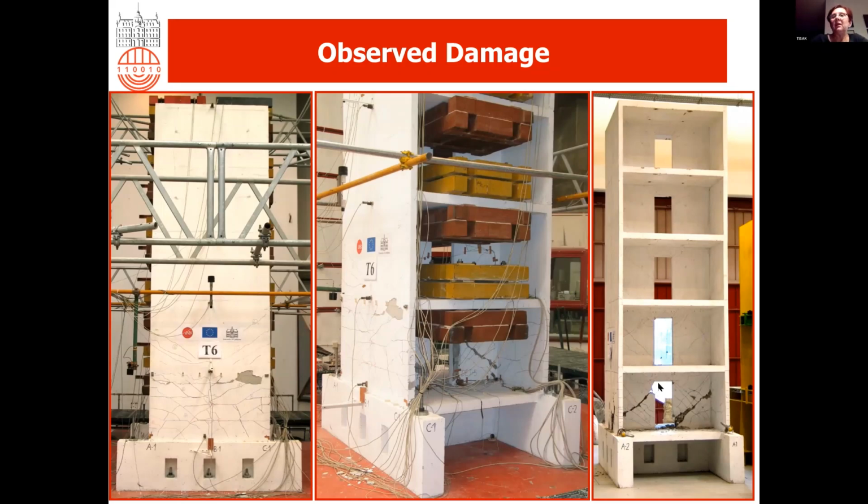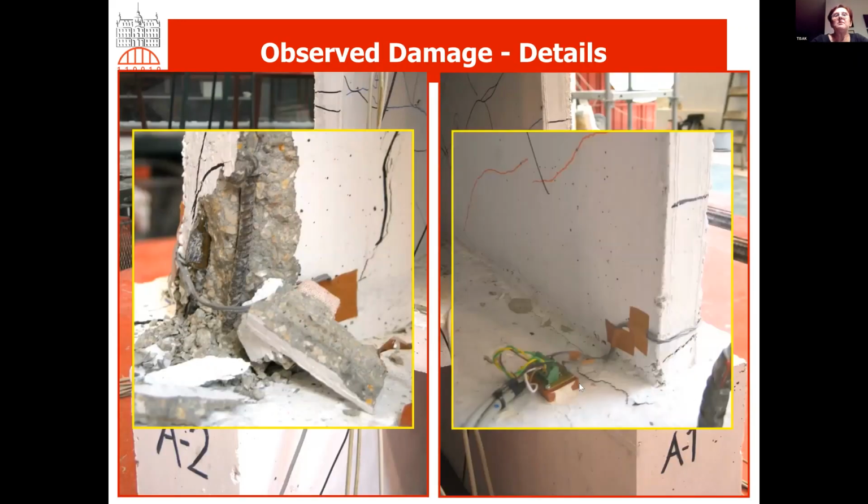Since we also had some additional masses here, the stiffness was really large. Nothing happened with the coupling beams, and the walls failed in shear. Locally, we obtained some damage in lightly reinforced corners without enough stirrups. In the corners which were properly reinforced, there was no damage.